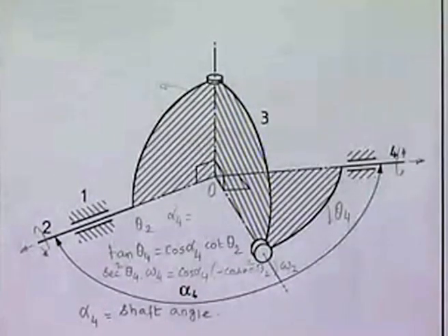However, we can use two such Hooke's joints in series to transmit a constant uniform angular velocity ratio. That is called compensating or self-compensating Hooke's joints, which are two Hooke's joints in series, which I will now show you in a sketch.